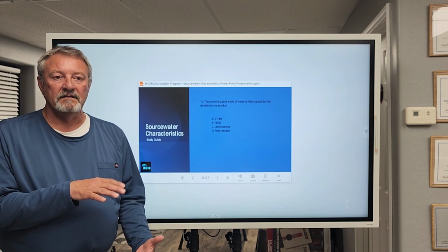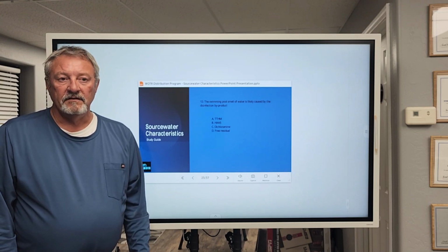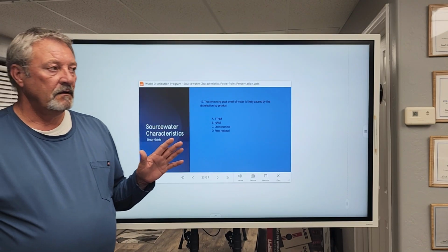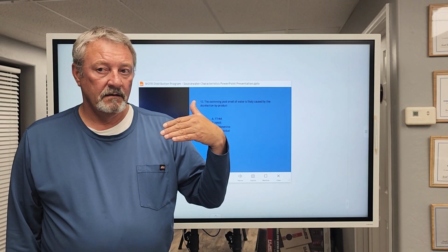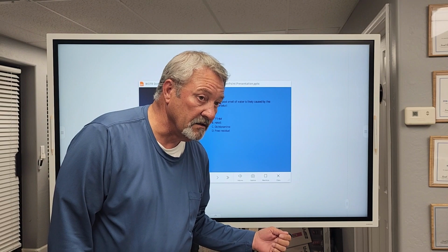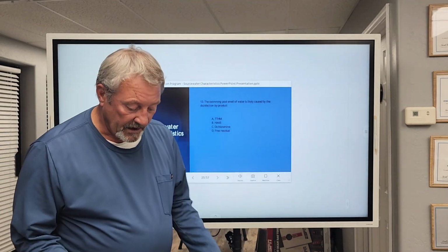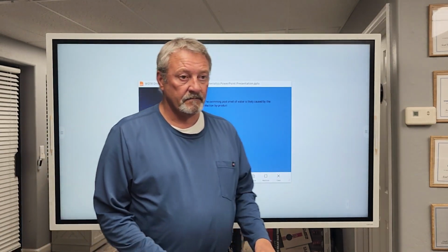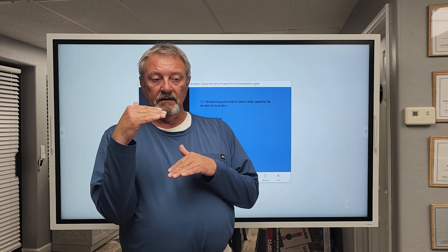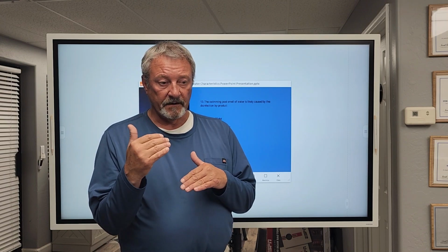They come in these buckets, either 3 gallon or 5 gallon buckets. And what do we train our staff to do? If they're going to open that bucket, walk away, and figure out which way the wind is blowing. If you open the lid to that bucket, number one, you don't want your face being close to that. Number two, you don't want to be downwind of it, you want to be upwind. Any empty space in that bucket is going to be pure chlorine gas. Chlorine gas is 100% chlorine. It's bad. Even a little bit can knock you on your butt, right?